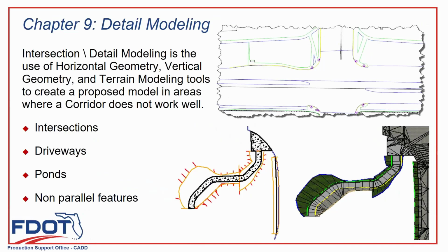I'm just thinking off the top of my head, but couldn't you do a roundabout with a corridor running around the center island? Yep. Well, technically, you'd have a lot of gaps for each leg, but for the apron you can go one way, and for the pavement you can go out to the edge of the pavement. You're right. And then each corner would have to be a linear template. Yep. And then there's a little area, and then you have the legs. And then you've got the median island, which usually tapers out.